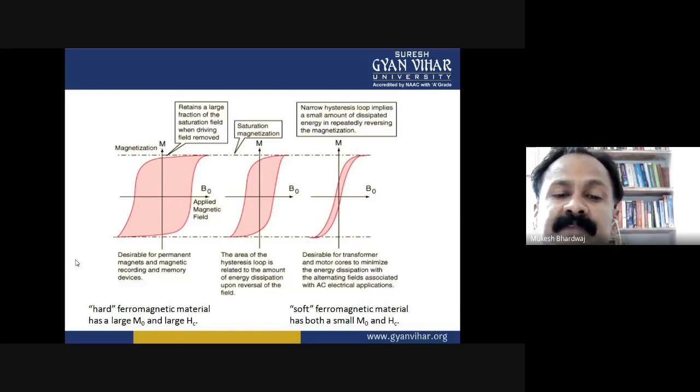Bs is the highest value of flux density, called saturation flux density, when the iron specimen is carried to saturation at both the ends of the magnetization curve. The residual flux density Br on the saturation loop is called retentivity. The coercive force Hc on the saturation loop is called coercivity.